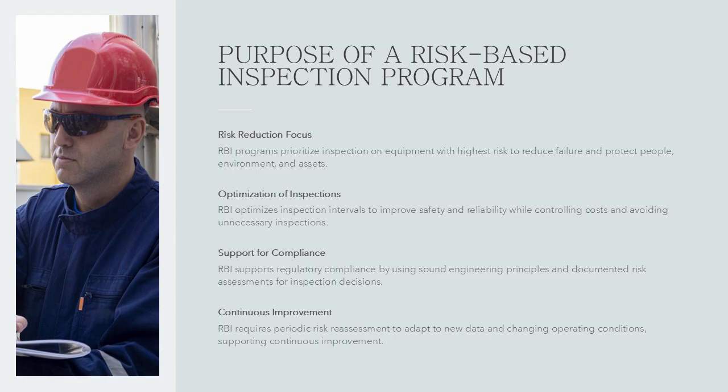RBI also supports regulatory compliance by demonstrating that inspection decisions are based on sound engineering principles and documented risk assessments. Another important purpose is to improve knowledge of damage mechanisms and degradation processes, allowing engineers to select appropriate inspection techniques and mitigation strategies. RBI programs also facilitate long-term planning by aligning inspection strategies with business objectives, such as extending equipment life, improving availability, and minimizing unplanned shutdowns.